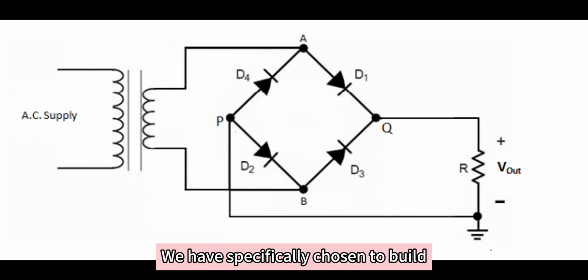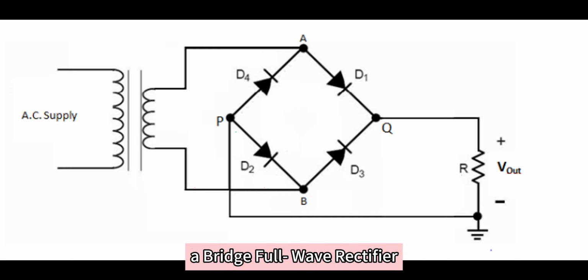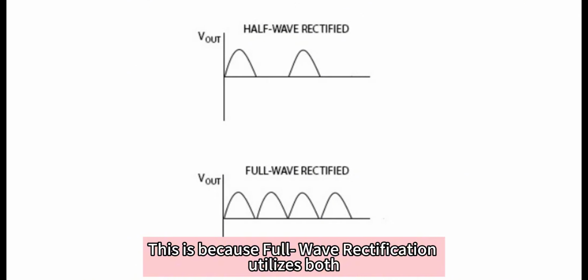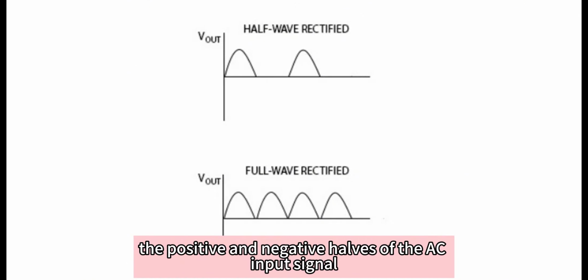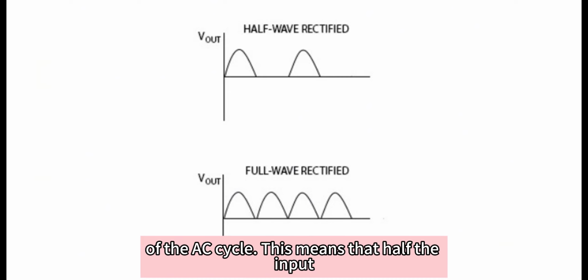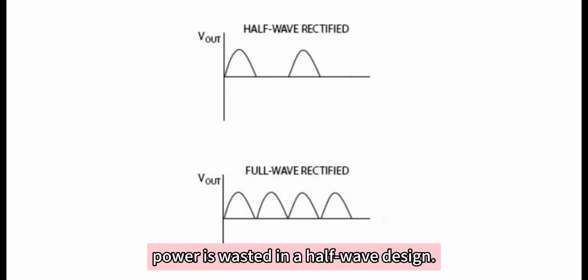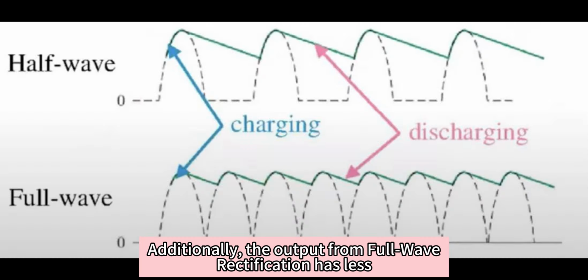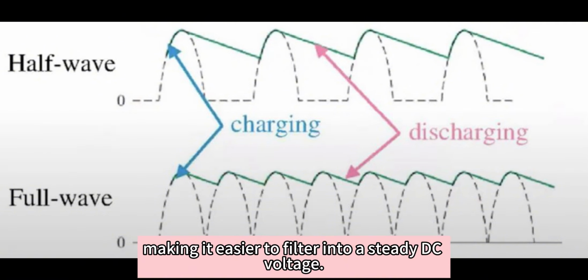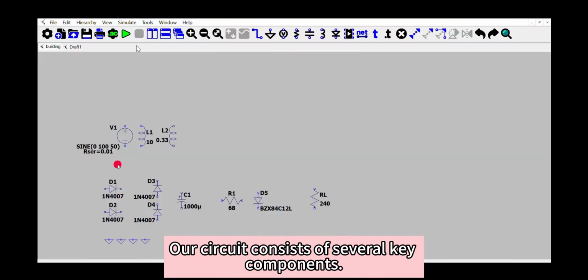We have specifically chosen to build a bridge full-wave rectifier, which is arranged as shown in the diagram. This is because full-wave rectification utilizes both the positive and negative halves of the AC input signal, while half-wave rectification only uses one half of the AC cycle. This means that half the input power is wasted in a half-wave design. Additionally, the output from full-wave rectification has less ripple compared to half-wave rectification, making it easier to filter into a steady DC voltage. Our circuit consists of several key components.